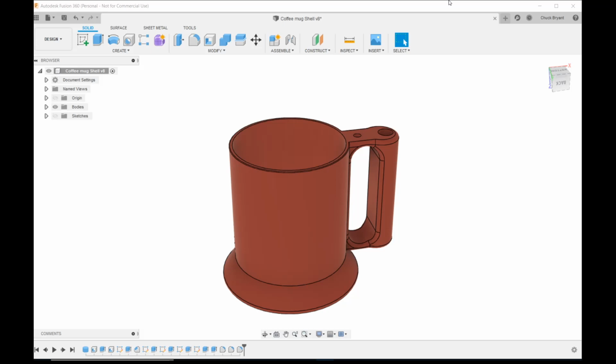After my last couple of Fusion 360 videos where I have demonstrated the value of creating a list of parameters, when you want to begin a model, you measure the things you want, even if they're just guesstimates, and you go into Fusion to modify, change parameters, and add user parameters, and you call them things like height, width, thickness, whatever makes sense to you that you can remember. You give them those names, and you do that ahead of time. That makes it a lot easier from a design standpoint because all your measurements are already in there. You're not having to measure things or refer to a drawing as you go along.